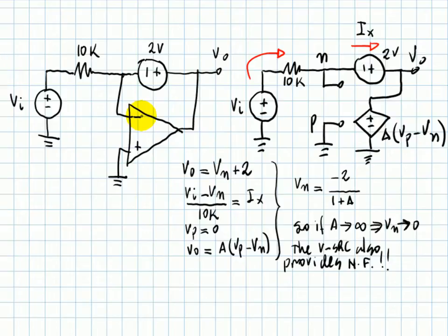No, not really. They are a sure bet, but in other cases we have to prove whether there is negative feedback. Let's try an ideal V source in the negative feedback loop and see whether that V source really provides negative feedback. I will make no assumptions.